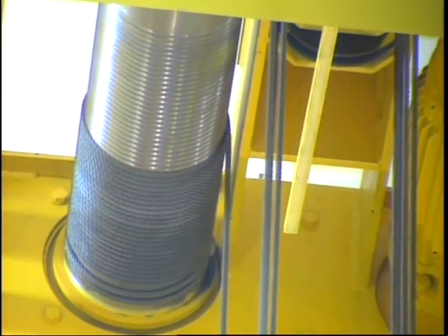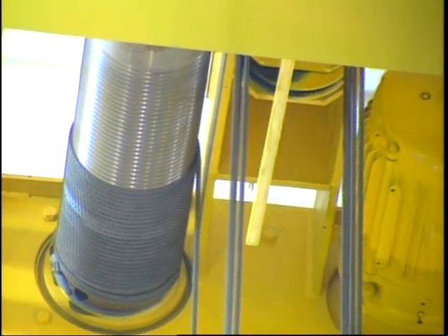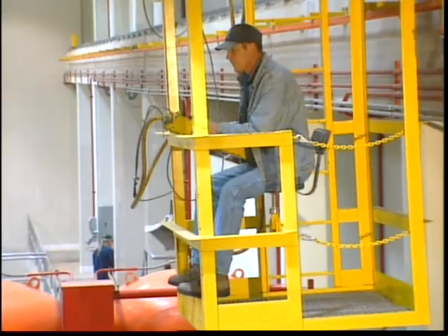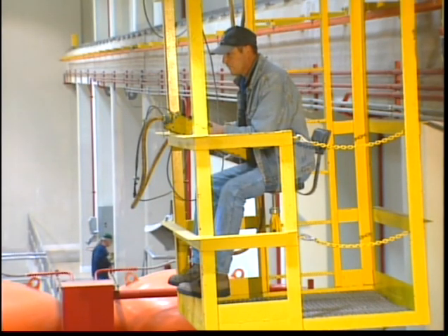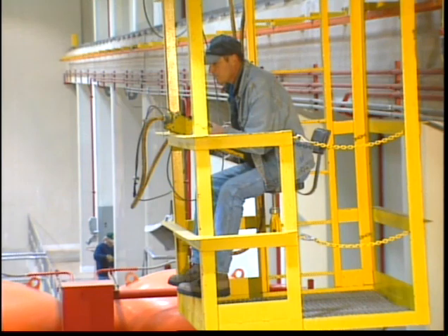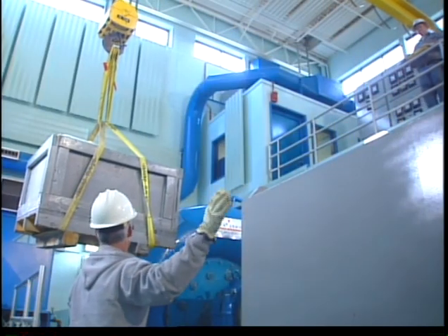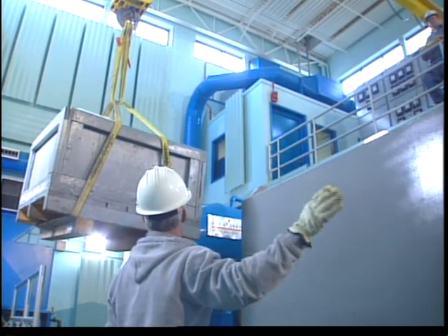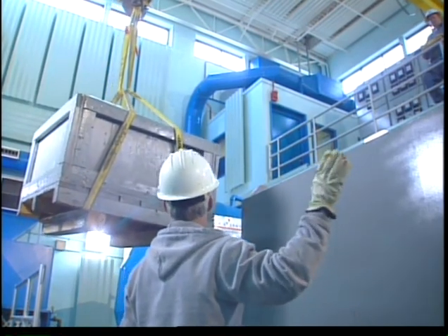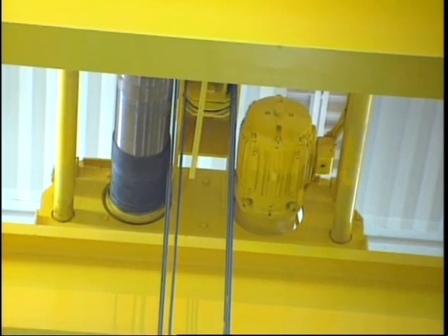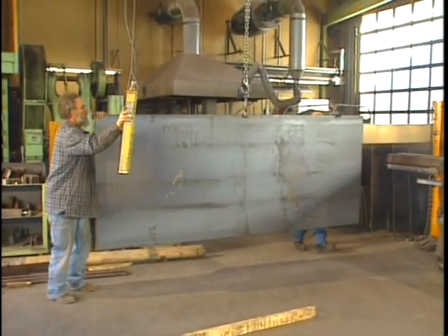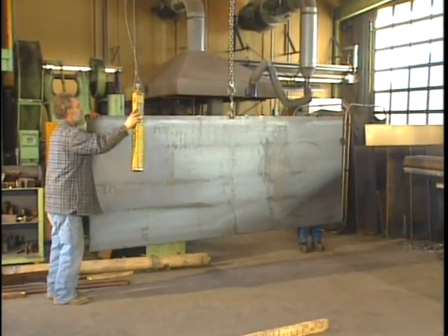The hoist motor should be used slowly and consistently. Don't rev or jog it as the load is moved. Use the crane's warning signal or horn to warn nearby workers that it's in use. As the load travels, watch it closely to make sure it doesn't get hung up or stuck. If it does, the crane may reach its load capacity quickly and the rigging components may fail. Raise the load only as high as necessary to clear the floor and any obstacles that can't be moved.